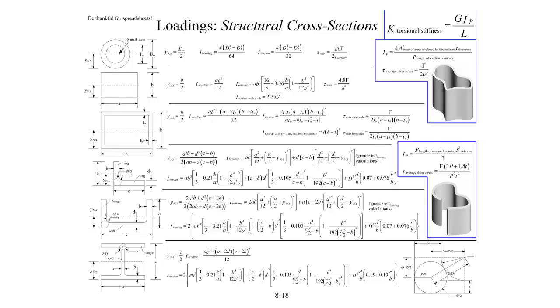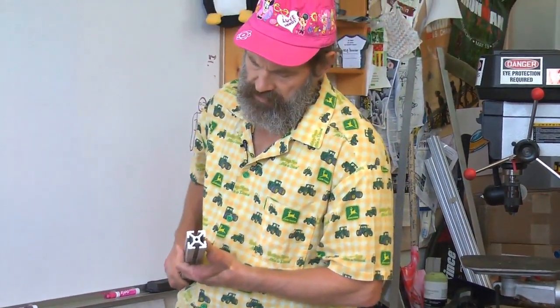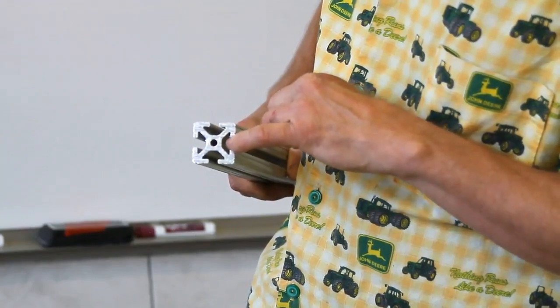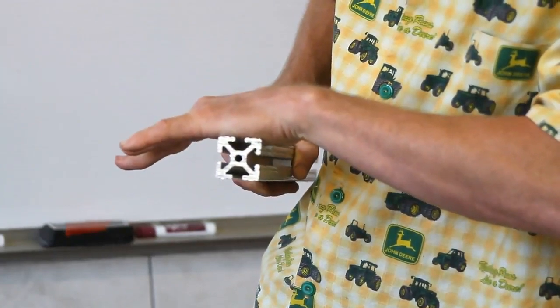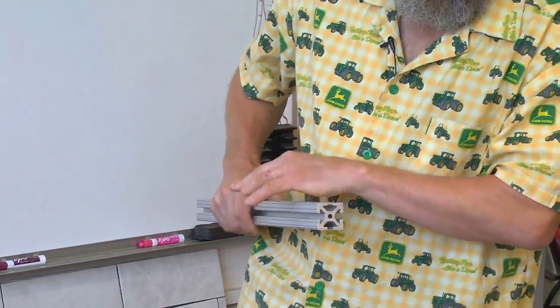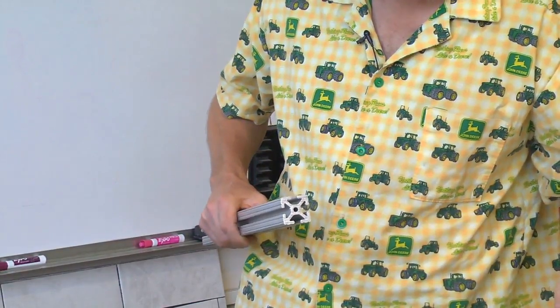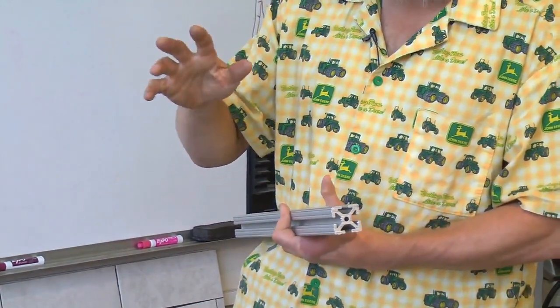Remember, you're designing your machine typically not just to last for a day or a week, but for years. Coming back to the stiffness question on detail, you can look at something like some of this modular aluminum structure, which is really handy, and it goes by a bunch of different trade names. It's wonderful because notice there are these dovetail structures in the sides that allow you to bolt stuff to it, and like a modular kit, you can very easily build up very complex machine frames out of this stuff.